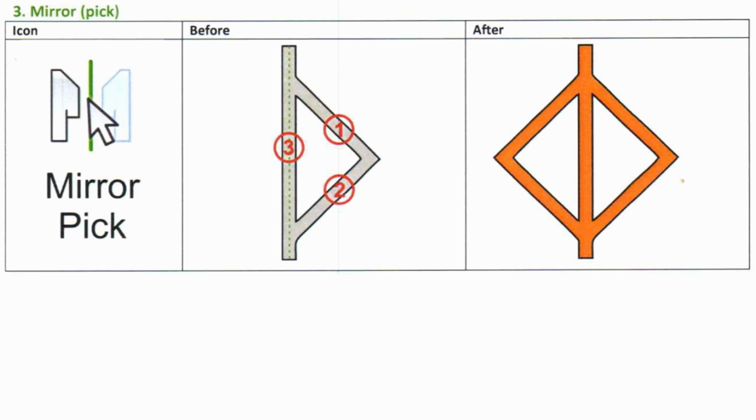Tips for precision: use Tab to cycle through available references when multiple options exist. Be mindful of click placement. The mirror axis defines both direction and orientation. Press spacebar to confirm if using the tool-first method. Use cases: mirroring fixtures, walls, or furniture across a center line. Duplicating layout geometry in symmetrical rooms. Aligning elements across grids or reference planes.